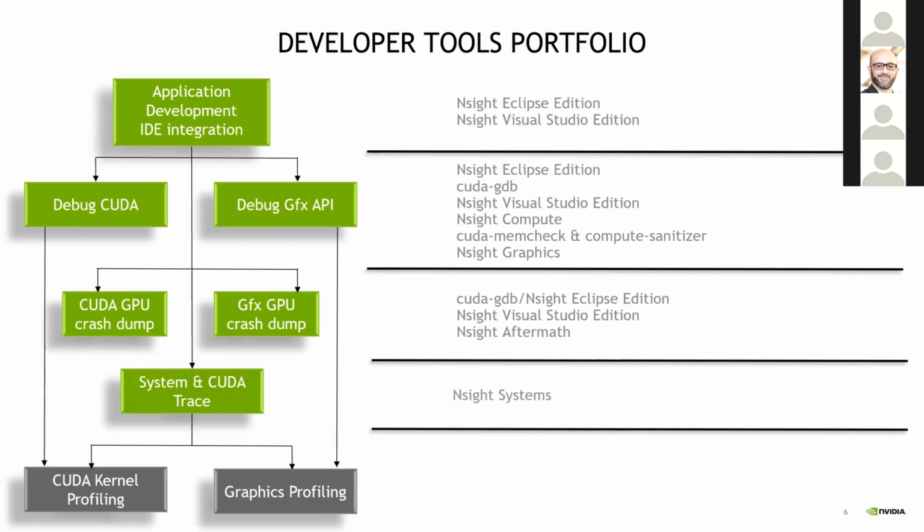And for the profiling part, we have two main components. The first component is Nsight Systems, which is there to provide the system level profiling, as well as application API traces in the form of very easy to use timelines and tables, and can also be used in the command line to dump the data to the console or export to a file.